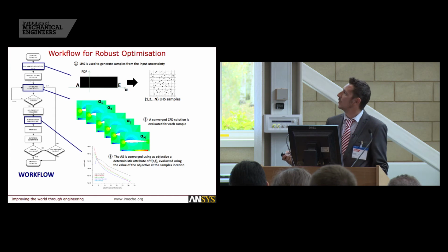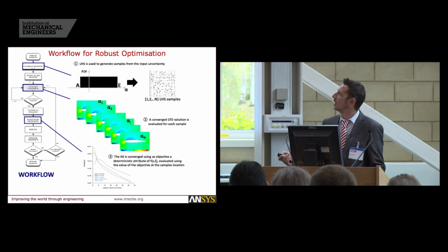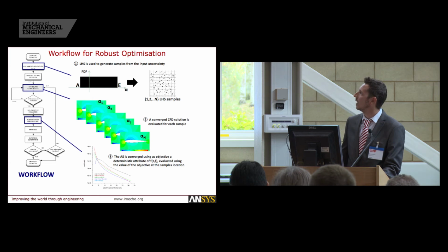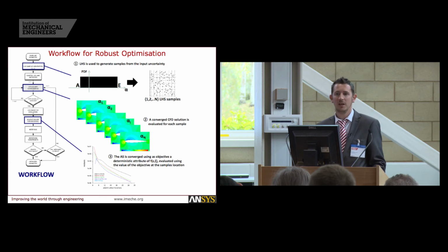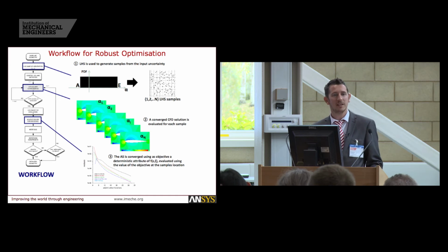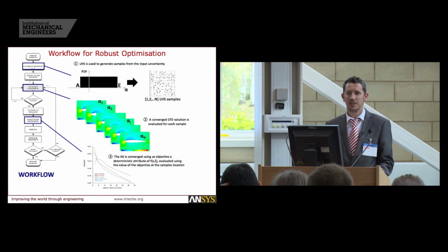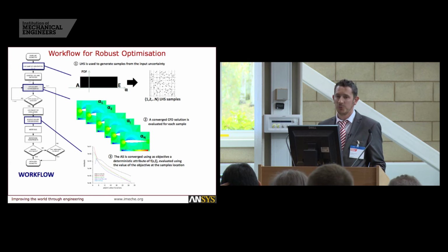So we started here by looking at the particular attack angle or the variation in attack angle, and taking what's called a Latin hypercube sampling procedure in order to sample out particular points in order to realistically define that definition for the parameter. And here we have all the different attack angles that have been analysed for this particular case, from alpha 1, alpha 2 up to alpha n. In this case, I think we took 20 particular angles of attack, which represented the sample points. And for each point, as we go down the tree, we solve the adjoint solution as we move down.